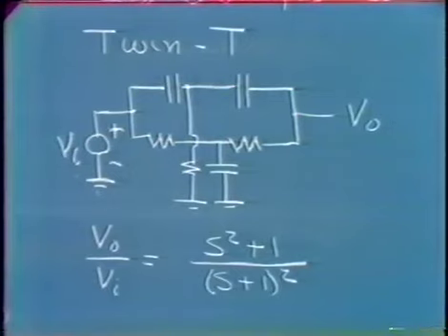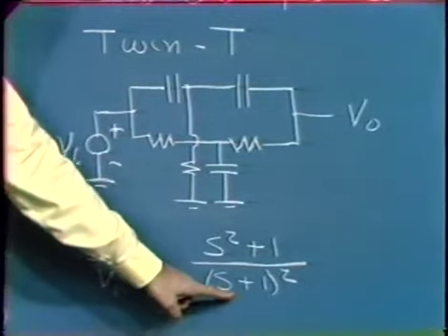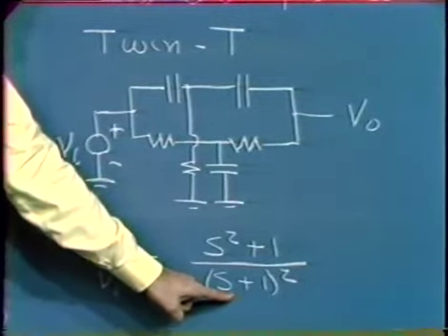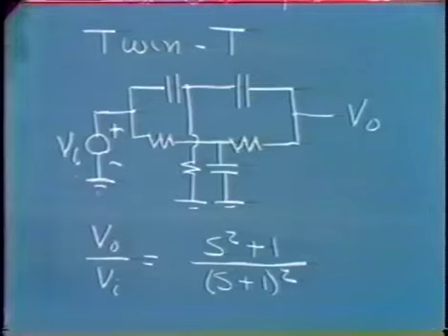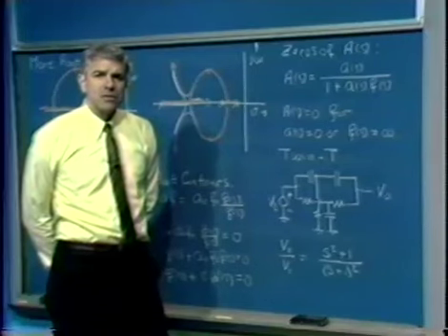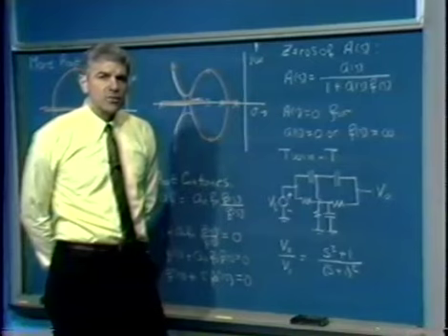And a possible pole location would be 2 real axis poles at s equals -1. Actually, I've taken a few liberties with this transfer function. There are 3 energy storage elements in the system, and consequently, we'd anticipate that there are 3 poles in the transfer function.